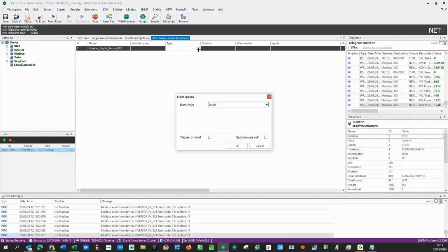On input change, could be on start of the BMS, on stop of the BMS, when the value changes, when a specific value changes, when the value is rising, falling, above a limit, below a limit, a specific timer, so every single second, and when an input changes. That's really nice. Input is enough for this case because I have 6 inputs. Every time one of those inputs changes, okay, let's do it.